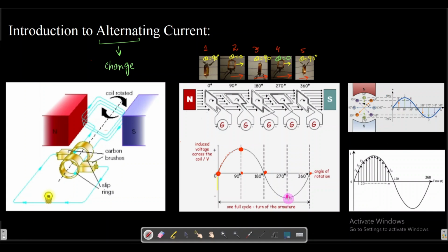So here this opposite direction is given to us by the Fleming right hand rule. Okay, now at the last position this coil again becomes vertical, and here the angle theta is equal to 90, the magnetic flux will be 0, so therefore the induced EMF becomes 0.